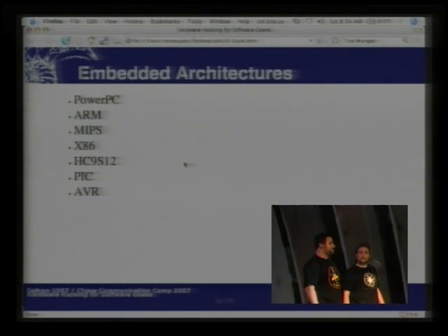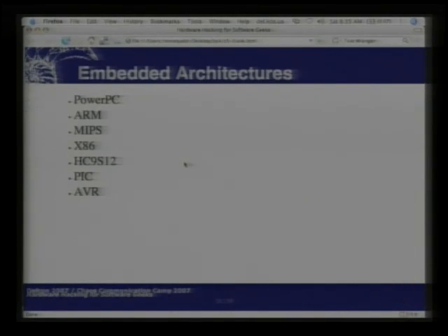A lot of the embedded chips these days have a system-on-a-chip architecture. Now, the way that works is they have a CPU core, which every chip in that processor family will use. And each processor in the family shares the same instruction set. In addition to that core, they'll have a unified bus which connects all the on-chip peripherals.